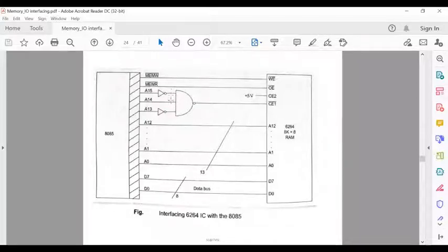All inputs are high, so that the output from the NAND gate will be low. According to the NAND gate truth table, the output of this NAND gate will be low if all the inputs are high. So if you have any input as low initially, you have to make it high. And how can you make it high from low? If you connect an inverter.